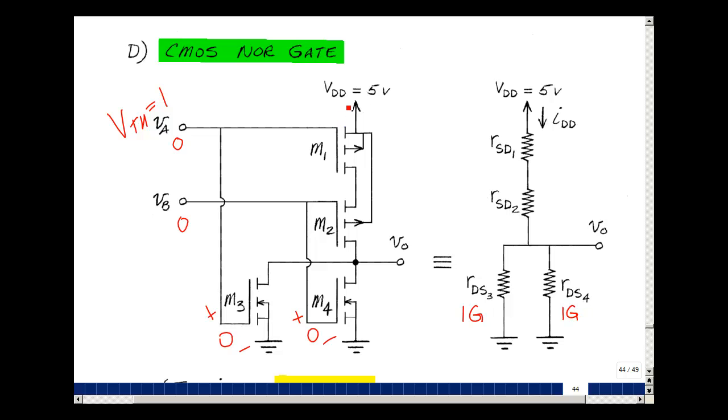This transistor up here, I can get the source to gate voltage. The source is 5 volts, the gate is 0, so there's 5 volts across here. We're greater than threshold. It would either be in the ohmic region or the current saturation region. But if I assume that this current is small, and then later verify it, by small I mean things like maybe in nanoamps or picoamps, then my guess for transistor M1 was that this would be a low resistance. I put a number on this to make it a little bit easier to do the algebra. This says 1 ohm, and these are gigaohms.